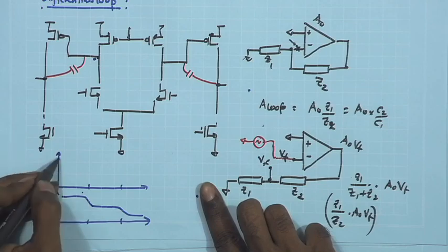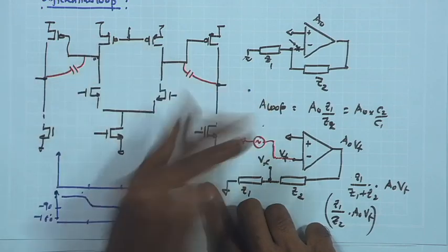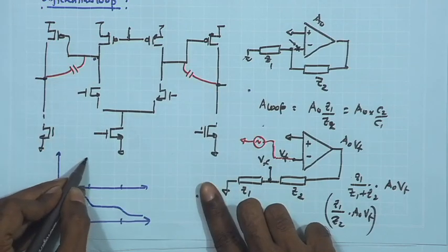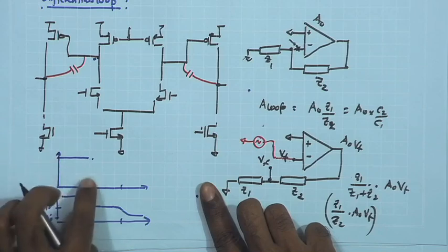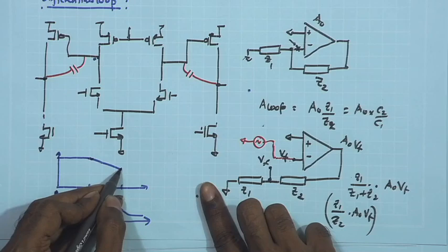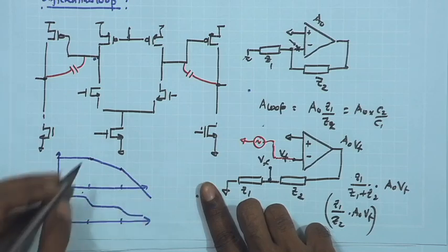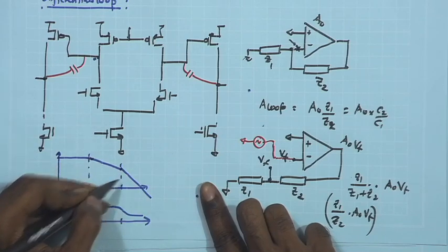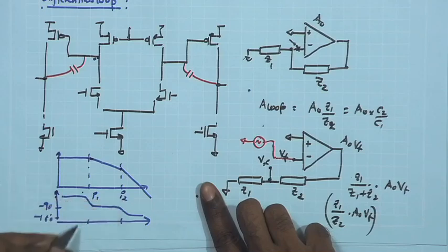And the magnitude response for the original case, the common mode case: after the first pole it is minus 20 dB per decade, and after the second pole minus 40 dB per decade. That is what we expect, if these are P1 and P2, which are almost similar for the two cases.